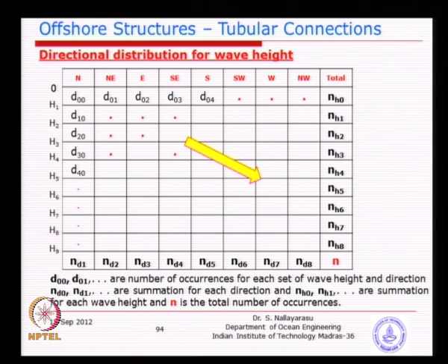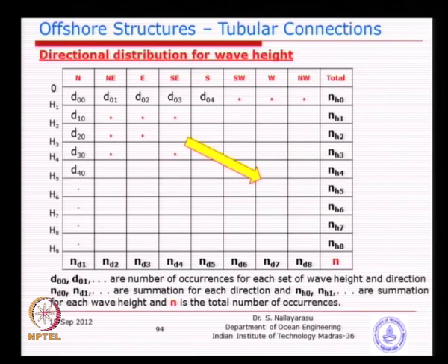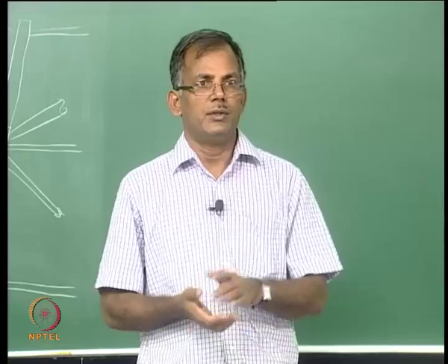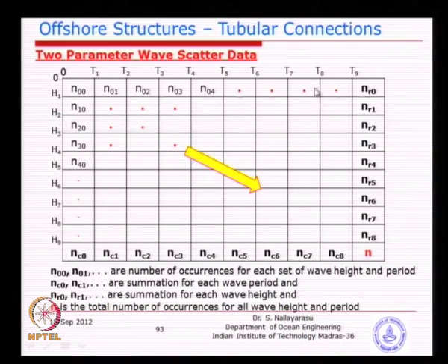Now, using this data you can actually link the direction with the wave period, because you have 2 linkages, just multiplications. In most of the projects we get these 2 tables provided from the previously measured data from the wave height measuring devices. And basically the reason why we need them is that you can multiply this with the ratio of this to this to get the corresponding directional distribution. So, that is the reason why we need these 2 tables.